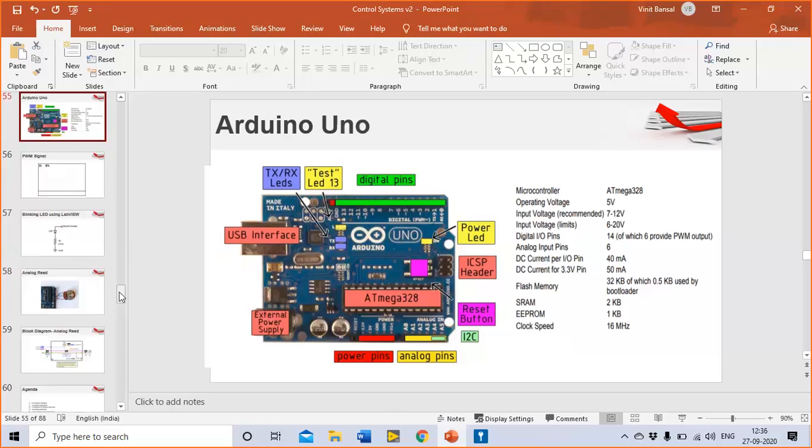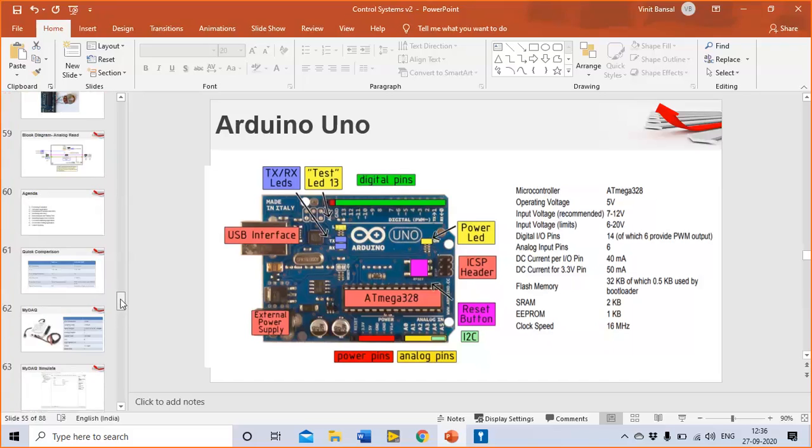Now, the signals on a satellite run in Gbps. The digital signals go at Gbps rates, and their analog communication signals go in the gigahertz range. So would 10 kilosamples per second ever be enough for those applications? Not really. And for resolution, in a lot of cases we need to go as high as 24 to 28 bits. So there are professional DAQ devices available in the market.